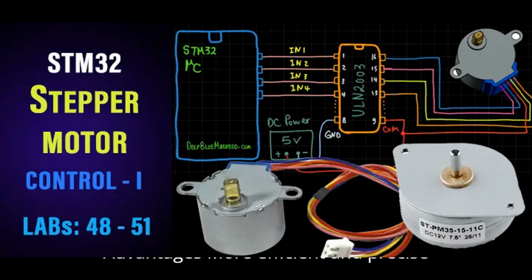Advantages: more efficient and precise than traditional stepper drivers. Reduced heat generation and lower power consumption. Higher torque at higher speeds. Applications: typically used in applications where performance is critical, such as in robotics, automation, and high-performance CNC machines. Examples: Leadshine AM882, ClearPath servos.